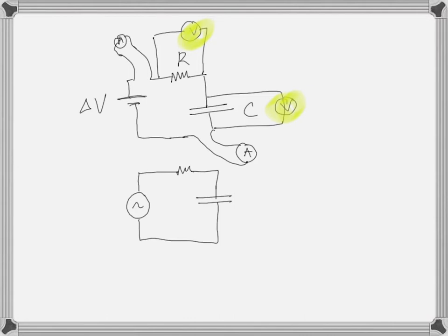Oh, and then we talked about grounds, right? We talked about the fact that the potential difference being supplied by your power supply is just the difference between the bottom terminal and the top terminal. But those terminals themselves can be at a particular voltage. So if either of these power supplies were 9 volts, it's a 9-volt difference between the top and the bottom. It doesn't mean that the bottom is at 0 and the top is at 9, or the bottom is at 20 and the top is at 29. We don't know what the absolute value of the voltage is.